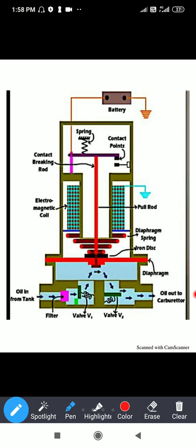Then afterwards the timing is set for the cylinder. As per that timing the magnetic flux is cut. When this magnetic flux is cut, both the shoes come into contact with each other. As the magnetic force starts to reduce, the spring starts to apply its pressure. The magnetic force reduces and the pressure of this upper load spring increases simultaneously. One side is reducing, one side is increasing the spring pressure.